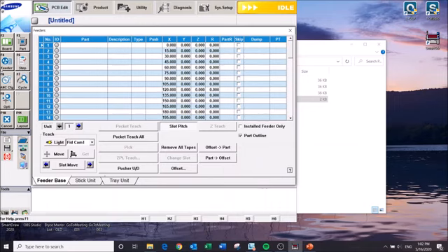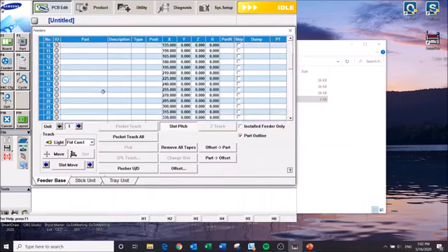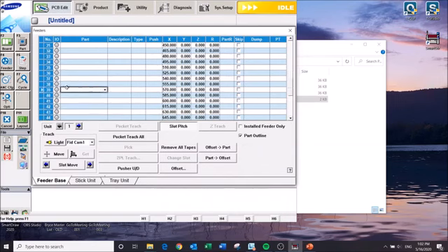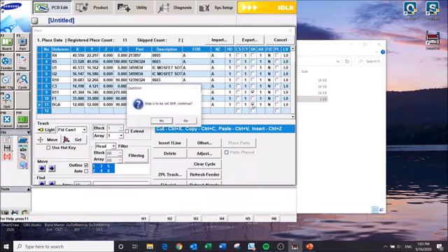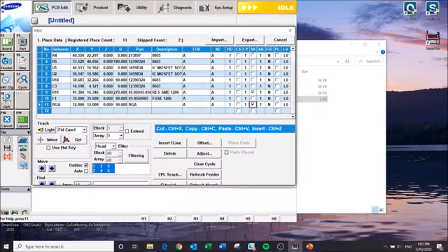So you can see right now we're looking at front side feeder base. You can manually assign those if you want to force them into a location. And the other thing you get is a step data or place data. And so right now we're looking at the order and the XY location, Z rotation, and part name associated with those.